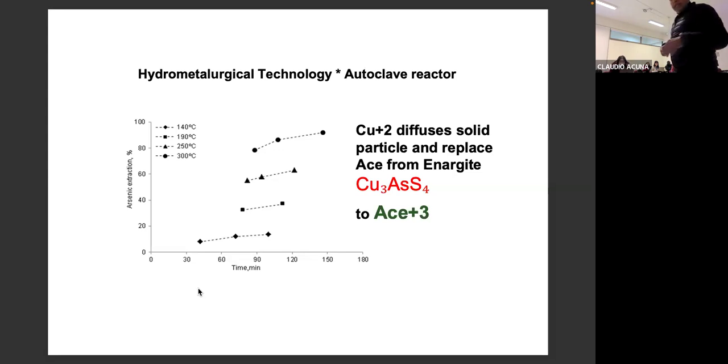Okay. So in this case, we reach up to 95, I don't know, 95, 99% recovery. More important, this is a big criterion. Listen up here. When you have a time in the range of 60, 90 minutes, 1 hour, 2 hours, it's feasible as a reactor. It's a common value. It's long, but not as long as days for biological reactors, wastewater treatment, where days is usual. But for a pyro-hydrometallurgical reactor, we are expecting 1 to 2 hours.